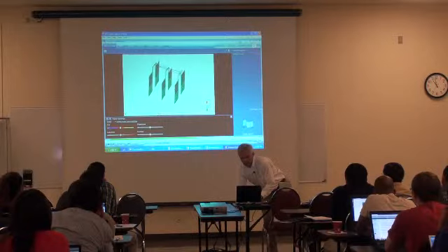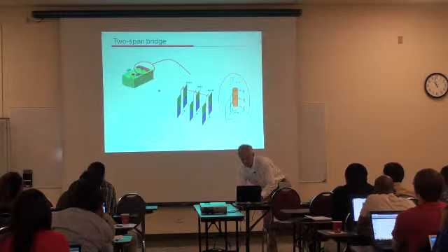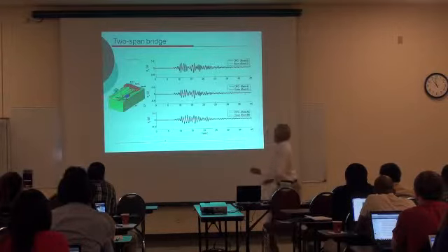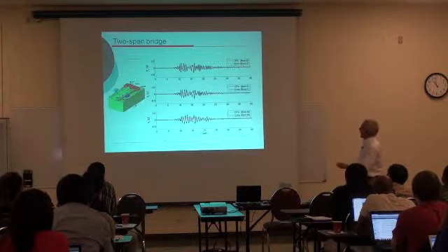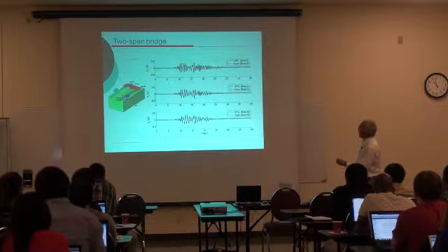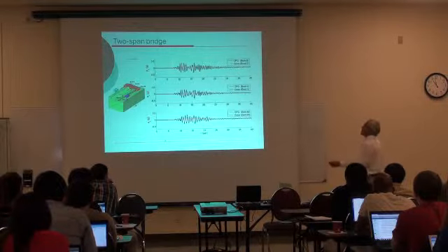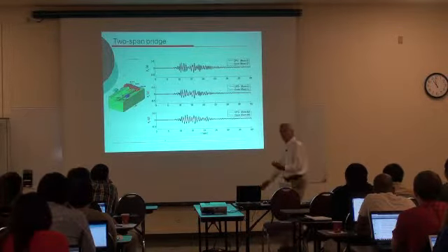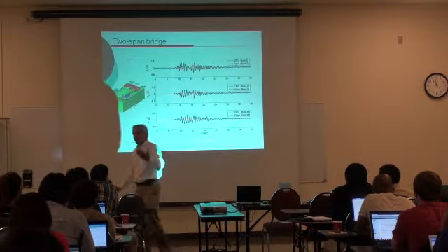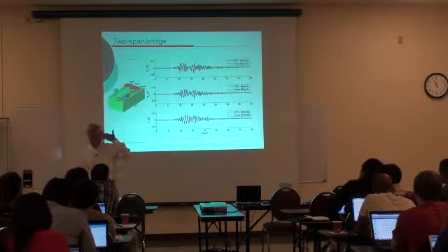And so let's go into that. So what I have here are the accelerations at the bridge bands. Again, centrifuge is gray and OpenSees is the black. You see that the response, at least in terms of the acceleration in that direction, was pretty good. That tells you that not always you need a very sophisticated model. It depends on what you're looking for.